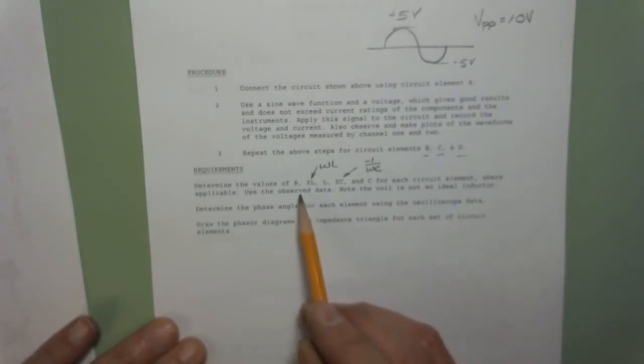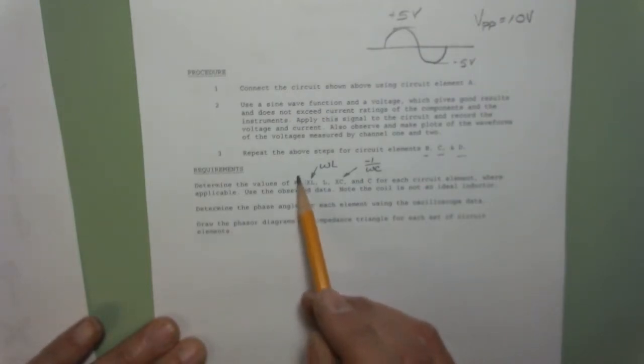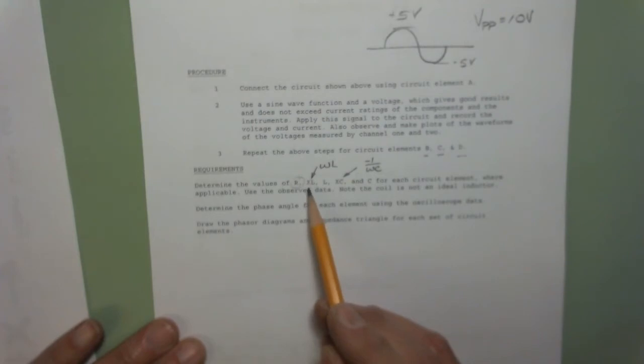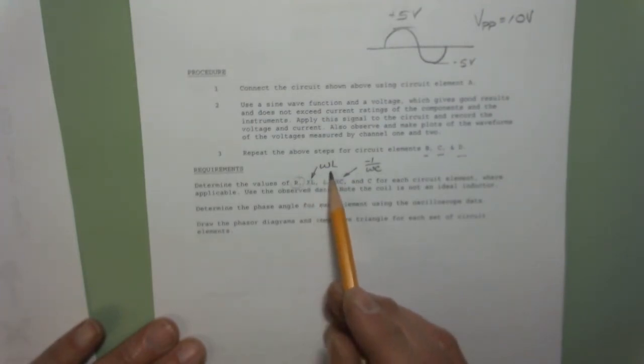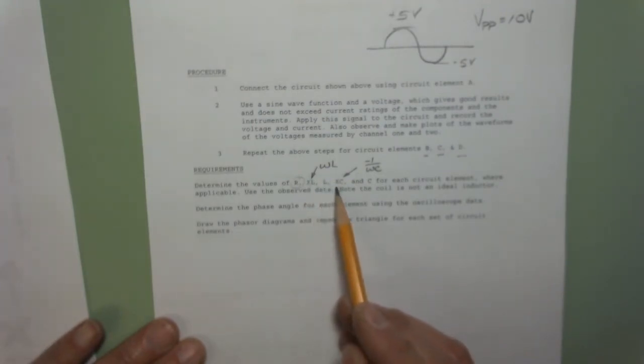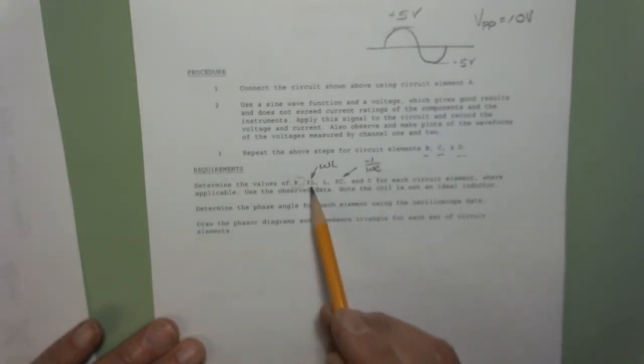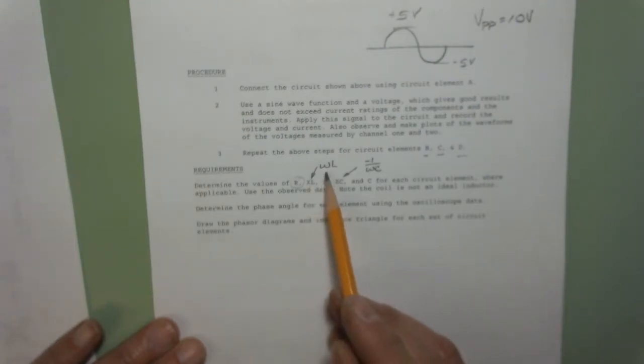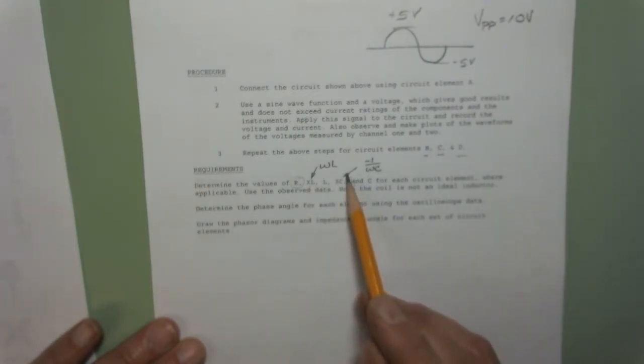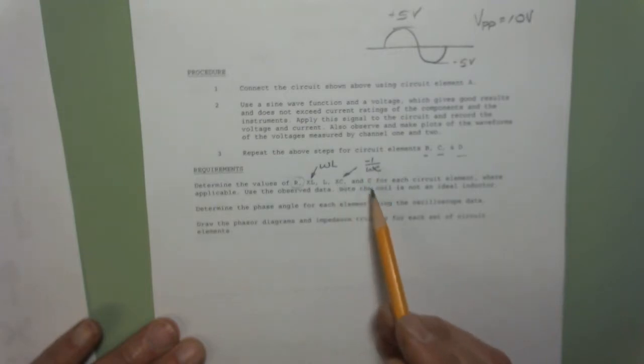Some of the requirements we're going to have to go through, and some of the nomenclature. We're going to want to determine the values of resistance, and then there's always this X sub L. That's kind of a shorthand for omega L. Of course, L is the inductance. X sub C, that's the shorthand for minus 1 over omega C. If you're thinking the shorthand X sub L for omega L doesn't make it much shorter, this one probably has some value, as X sub C is minus 1 over omega C. And finally, the exact value for C. So if you're stumped on X sub L and X sub C, that's what's going on there.